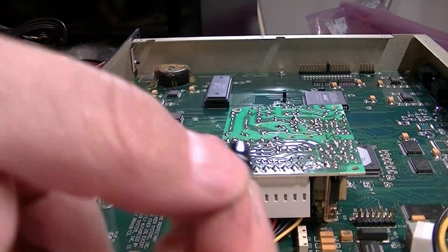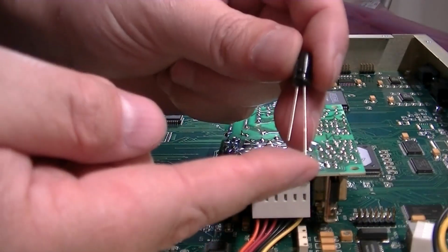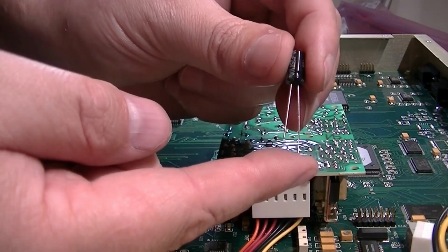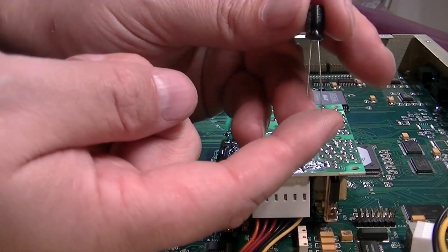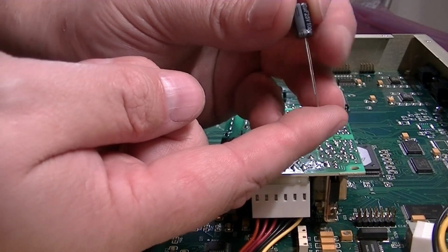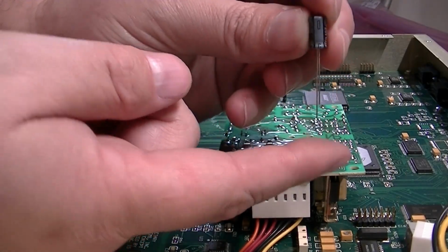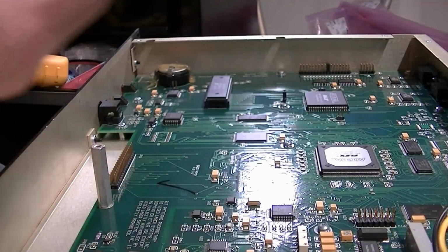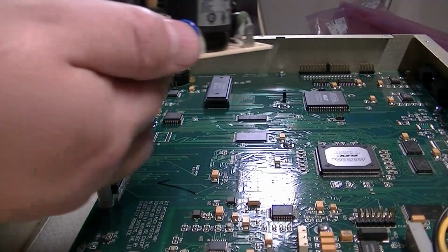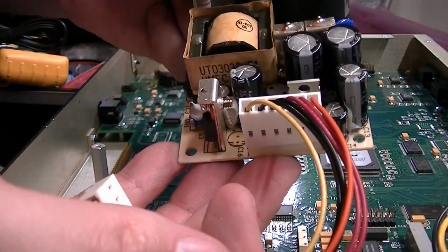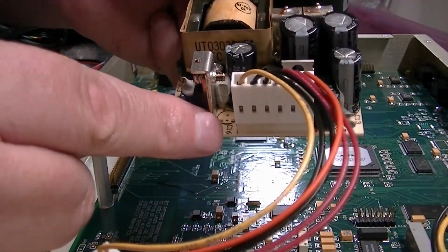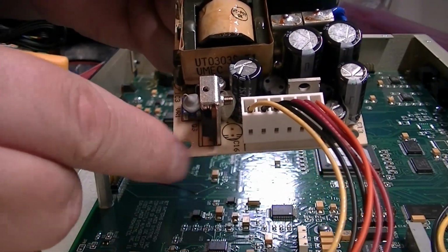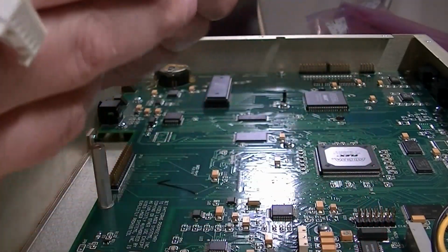Okay, remember when playing with electrolytic capacitors, always remember to put them in polarity correct. So on a new capacitor, the long lead is positive and the negative lead is marked on the case with a stripe like that. And on the board here, you'll see like a little indicator of negative in the pattern on the printed circuit board.